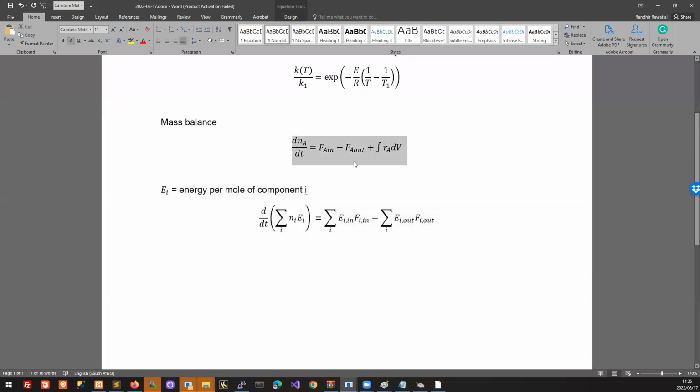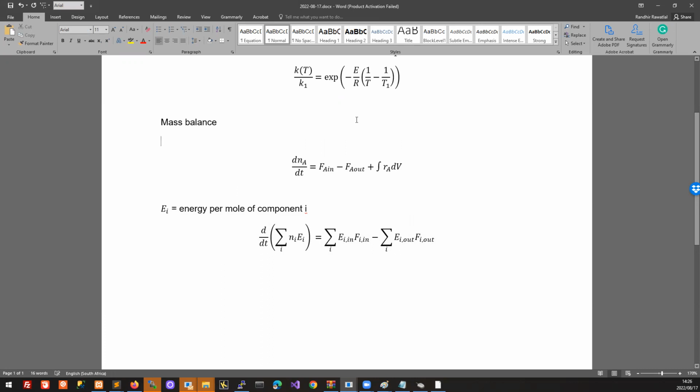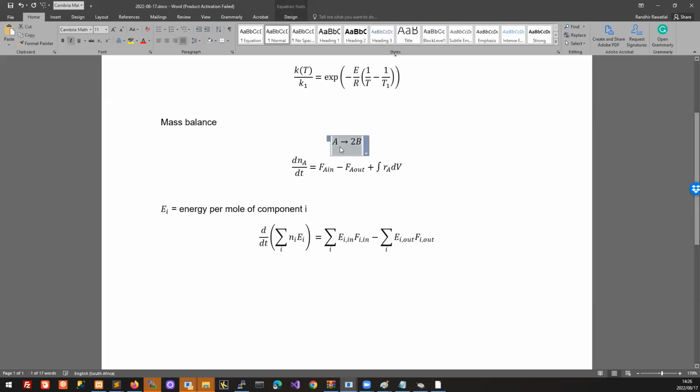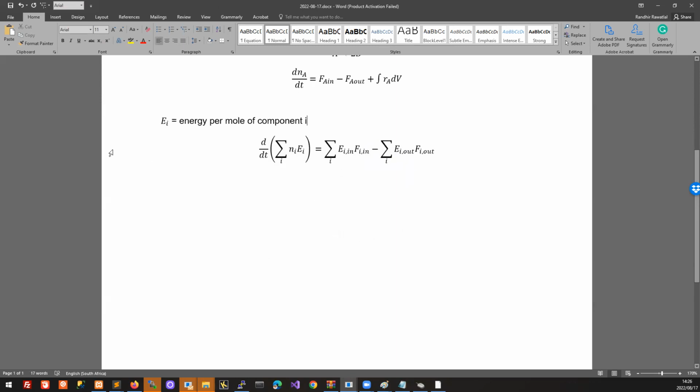And by the way, just a note that when we write the mole balance, of course, the moles are not conservative. So you have conservative properties: energy, mass. We consider those conservative properties of nature. Number of moles is not conservative. In the same reaction, you can have more moles appearing than you had in the first place. There's nothing wrong with that, right? So your mass can stay the same, but your moles could be increasing or decreasing. That's why in the mole balance it's pretty automatic to add that in, but we can't have that in our energy balance. That's just a principle for us to bear in mind.